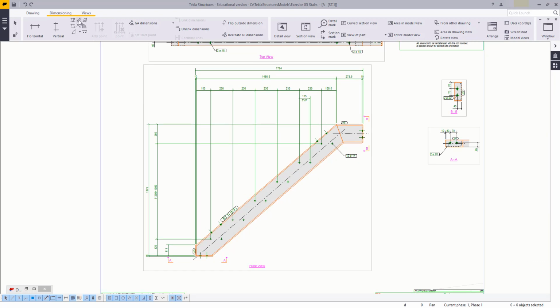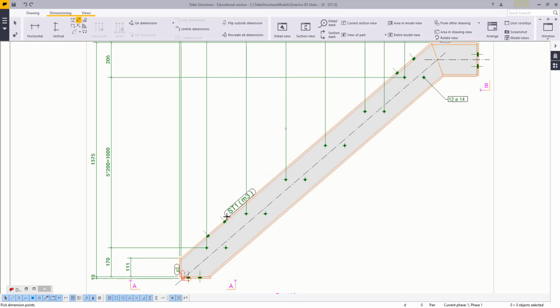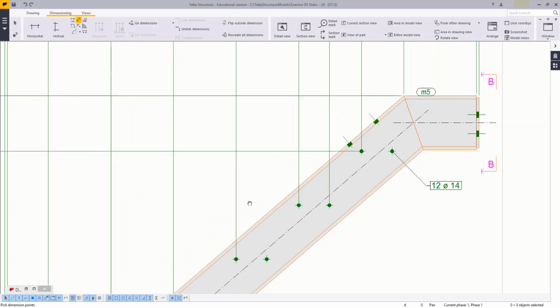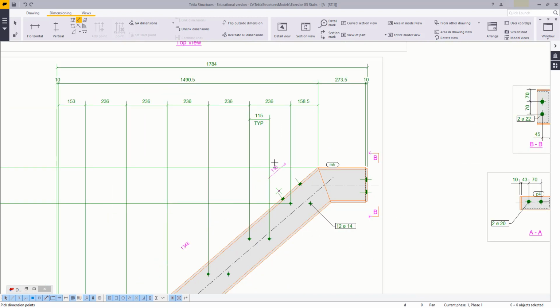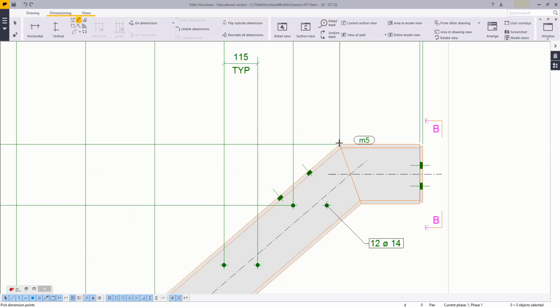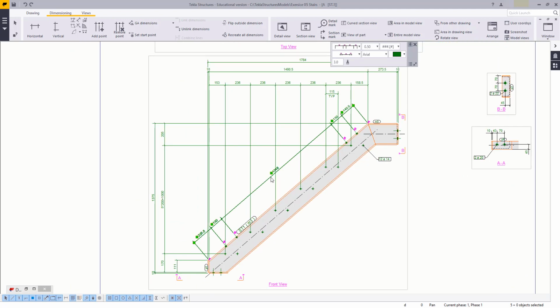Next, we would like to do these holes on top. Now, I don't really trust my start and end point, so I'm going to take a point that I know the height of as my first and last point, as that determines the angle. Here I'm going to take the last point and then end up again with the top there. At least then I know these bolts are always nicely aligned because of the first and last point bit.